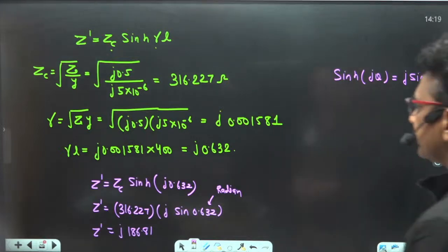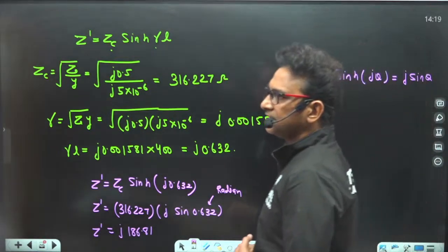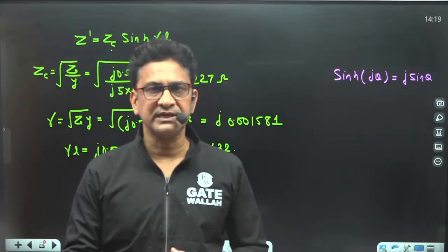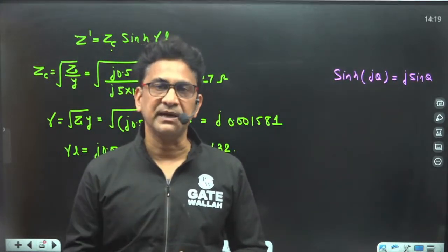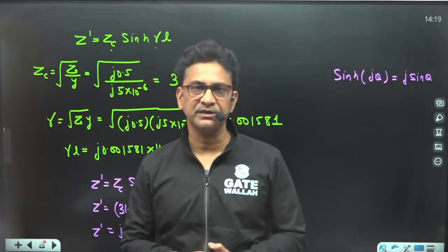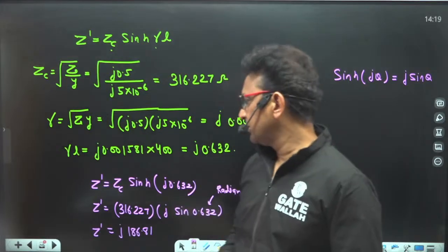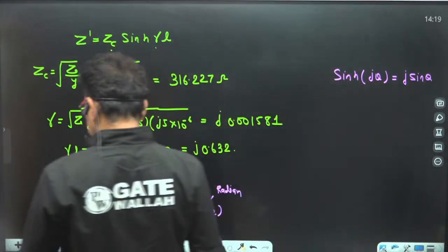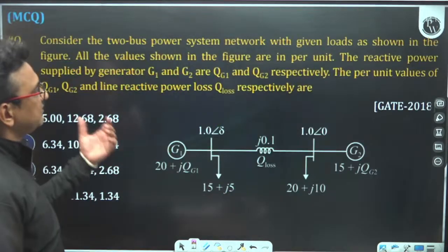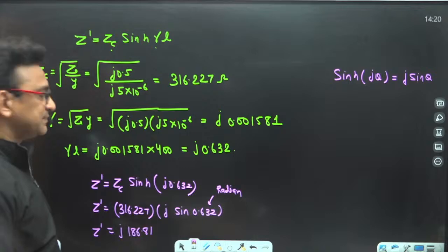See, how we classify whether the transmission line is a long, short, or medium transmission line. It is according to the overall length of the transmission line with respect to lambda, and lambda is 6000 kilometer if we assume the frequency is 50 hertz. So, any transmission line whose length is above 200 kilometer, whether it is 250 kilometer or 260 kilometer, for both it would always be a long transmission line.